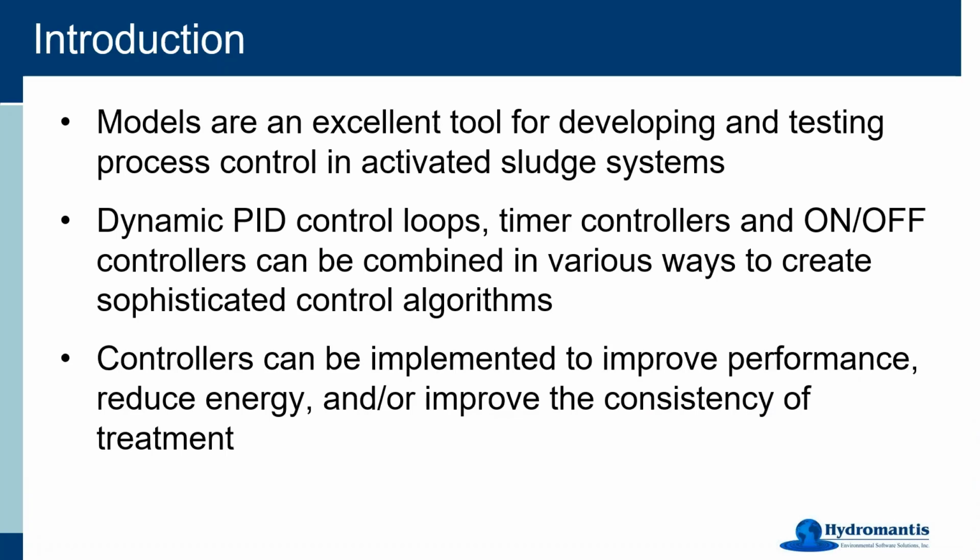Okay, so as I'm sure you know, being the modelers that you are, models are really an excellent tool for analyzing wastewater treatment systems and specifically for testing process control on those systems. And there's lots of ways that you can implement a control in the models that we create. So you can have PID dynamic control loops. You can have timer controllers that activate at certain times on a sequence. And then you can have on-off or high-low controllers that can do various things. And of course, the most interesting aspect of these is when you're able to combine them together to do cascade control and get to really sophisticated things that you can do.